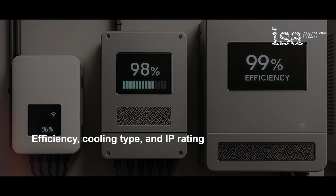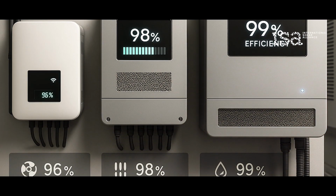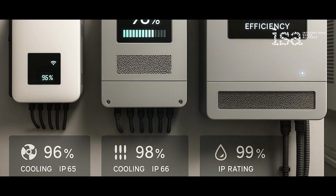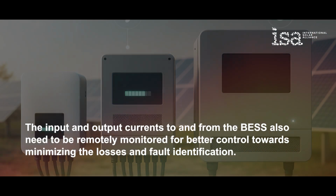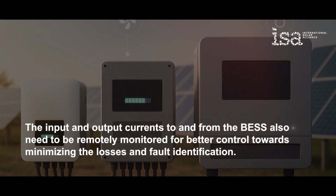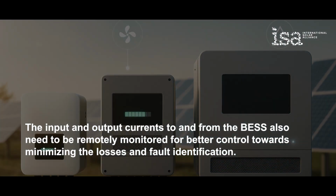Consider efficiency, cooling type, and IP rating. Communication and monitoring features: power generation string-wise is vital and needs to be monitored. Also, the input and output currents to and from the BESS need to be remotely monitored for better control towards minimizing the losses and fault identification.